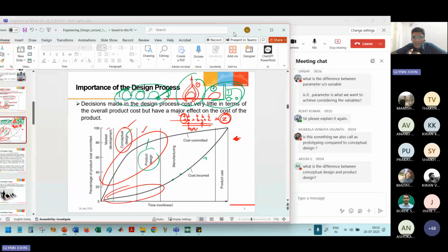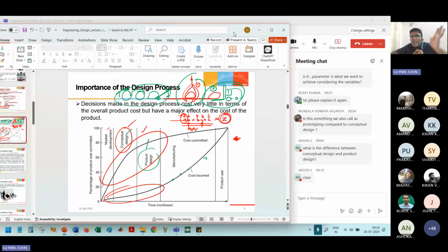When you say product design, we mean the entire process, starting from identifying the customer's needs to delivering the final product. That entire thing is product design. Conceptual design is one small part of it. Embodiment design is the next part of it. Then after that, you'll do a detailed design, which is also a part of embodiment design, right? So embodiment design is a slightly broader spectrum. It starts with performing calculations, analysis, modeling, detailing, and so on. Finally, before you go in for manufacturing, you'll build a prototype and actually test it. Then you'll perform smaller revisions. Then after that, you'll go for manufacturing.